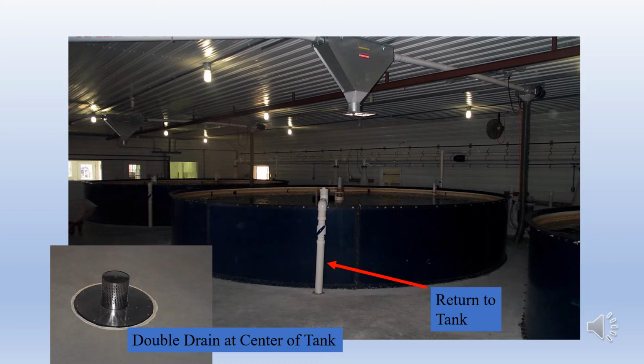Once all these solids are taken from the water, the rest of it is dealing with the solids that are not affected by gravity, what we call suspended solids, or in some cases colloidal solids, and we'll see a couple of ways to get rid of those too.